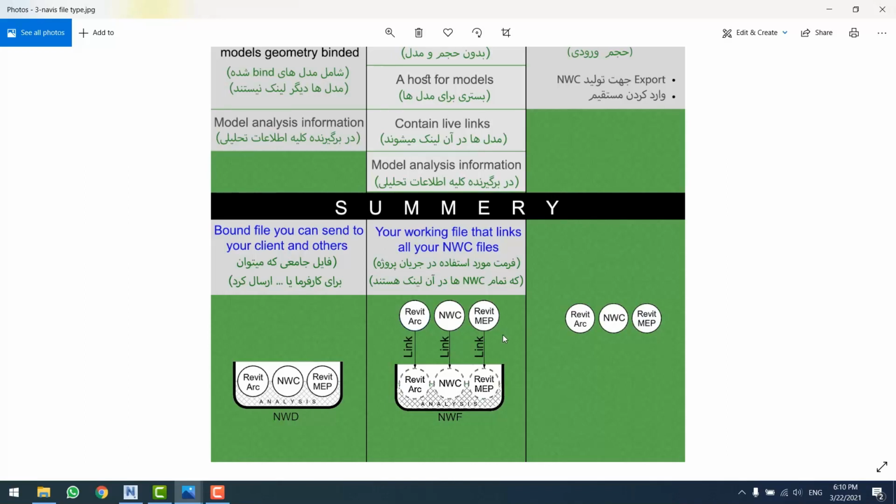Excellent! Absolutely less than 3 megabytes. But what is the reason? Because when you save your NWF file, the NWF file does not consider the size of the NWC files. Why? Since they are attached to the NWF file. So what is saved in the NWF file? Or, let me ask, what does affect the size of the NWF file? Certainly the analysis process. Do you remember the folder?